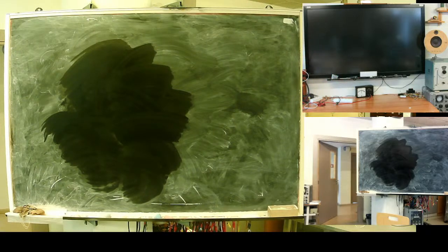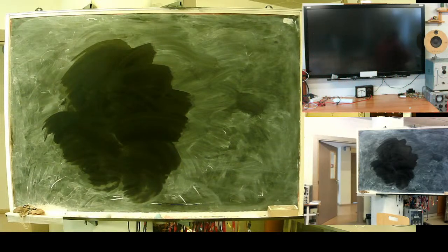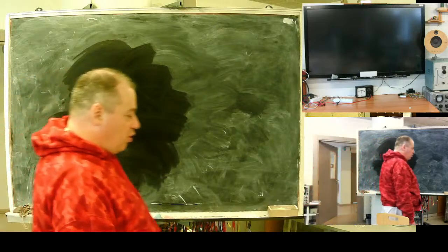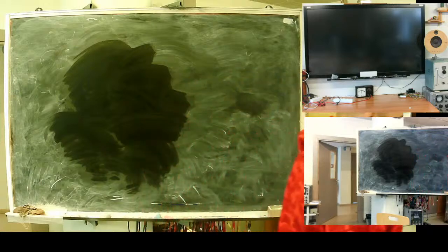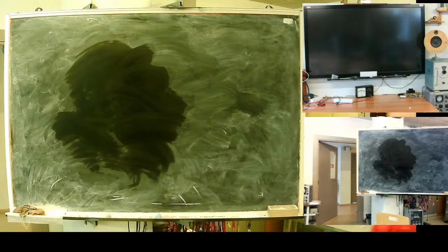I'm only pointing my finger. All distance protection can operate falsely in case of asynchronous regime, in case of synchronous swing. So they should be blocked and unblocked only on the basis of rate of change, or plus if you see negative sequence current or voltage, then you can operate.